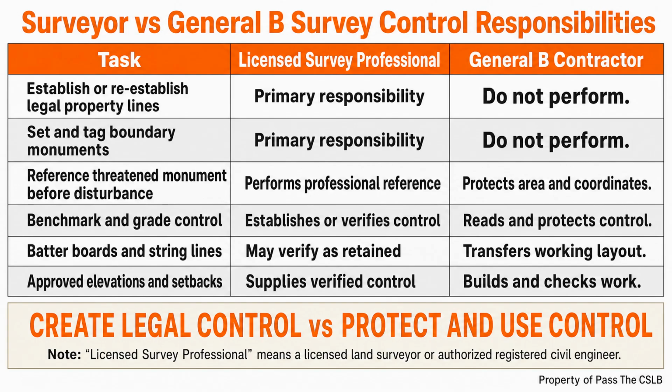The same principle applies to grade stakes. The contractor does not need to treat every temporary stake like a permanent monument, but the contractor does need a plan for preserving the information before excavation removes the stake. That may mean documenting the stake, transferring its elevation, or coordinating replacement through the surveyor when the control is outside the contractor's authority.